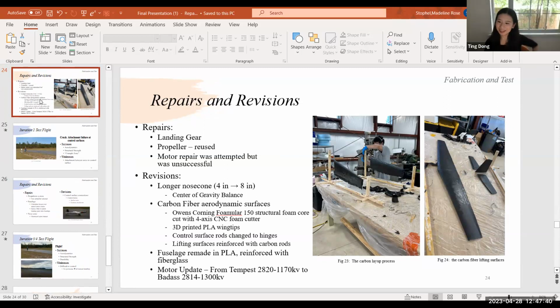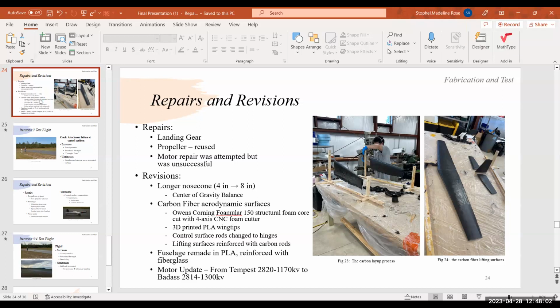We're going to have all of our avionics inside the fuselage. From people I know that have done carbon fiber fuselages in the past, they've had to use antennas protruding from the fuselage so they're not blocked by the carbon wrap. I heard it described as turning the whole plane into a Faraday cage. That's something we were concerned about when we wrapped our plane in carbon fiber, but it was not an issue.